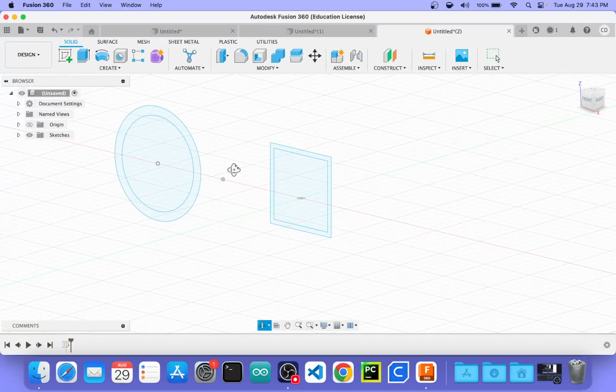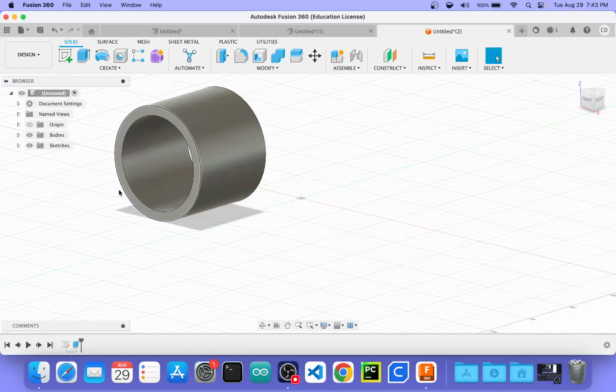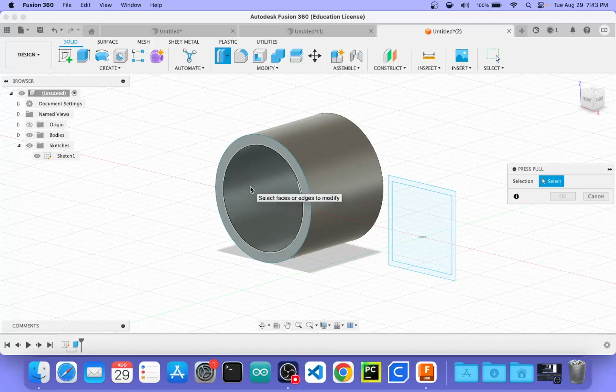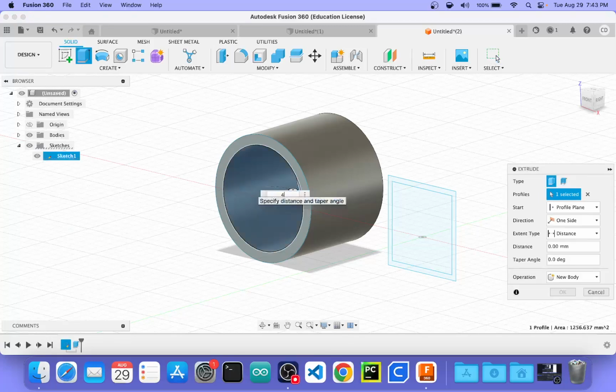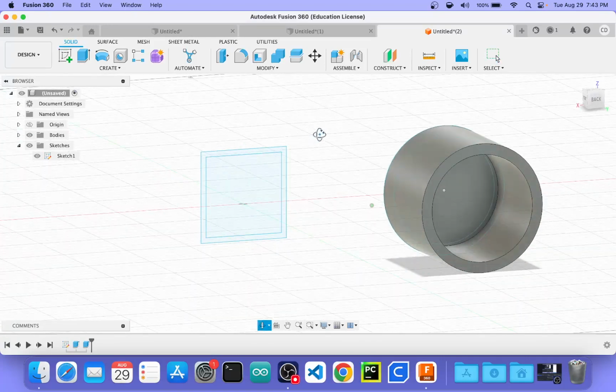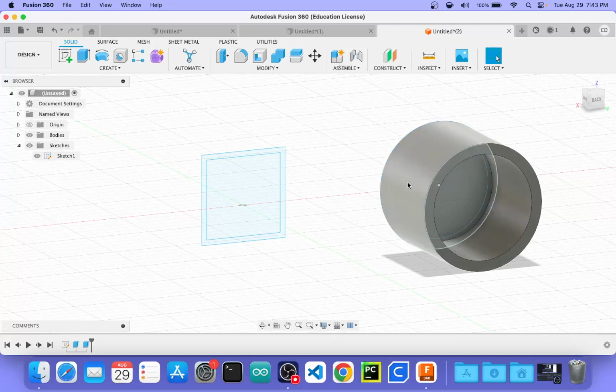And so you've probably noticed this, but when you extrude your first one, let's say we want this one 40 millimeters tall, the sketches disappear. You can control the visibility of everything over here on the left. Like I said, you may have already figured that out, but in case you haven't, that's the way you do that. And so on this one, if I want to have a little base here, I could highlight this interior part of the sketch, extrude it by 4 millimeters, which is the same depth as the walls, and then I've got a hollow cylinder here, which I could add embellishments to.